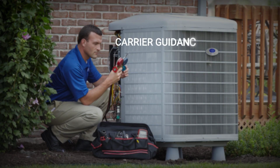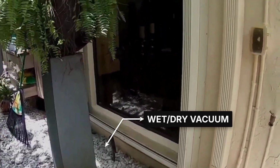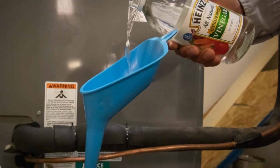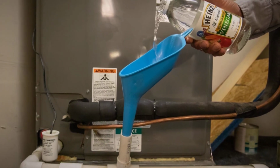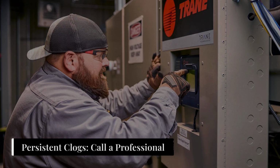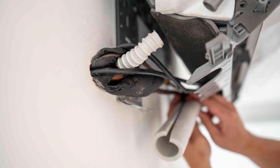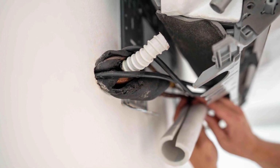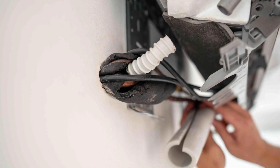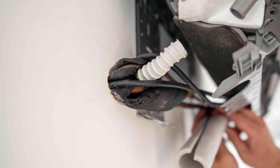Carrier separates those jobs on the same drain line page. For a clog, it describes suction from a wet or dry vacuum at the outdoor exit. It reserves distilled vinegar as an option applied through the access point. Persistent clogs go to a professional. Trane draws a similar line. Its clogged condensate guidance describes technicians using a vacuum, wet or dry vacuum, hose or snake to remove the obstruction, followed by drain line cleaner and water.